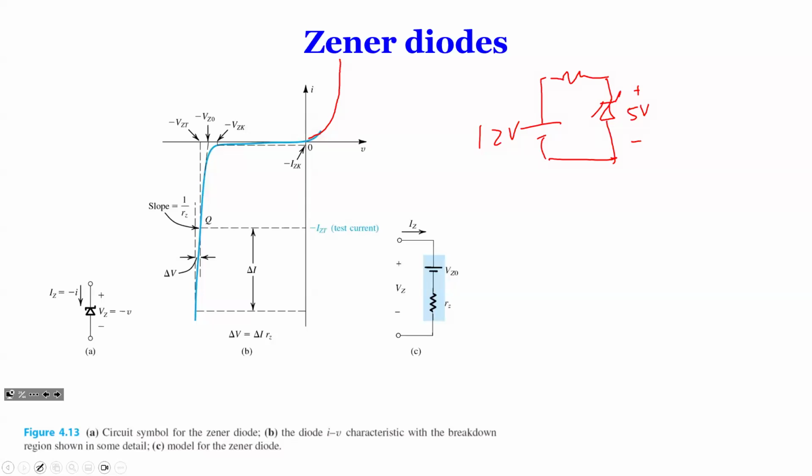You see the diode has a little tilt, the special symbol for a Zener diode. And whatever the resistance is there, let's say you get 1K. Then you can calculate the current: 12 volts minus 5 volts divided by 1K. That gives you 7 milliamps. So that's the current in the circuit, because the Zener diode gives you 5 volts, a constant voltage.